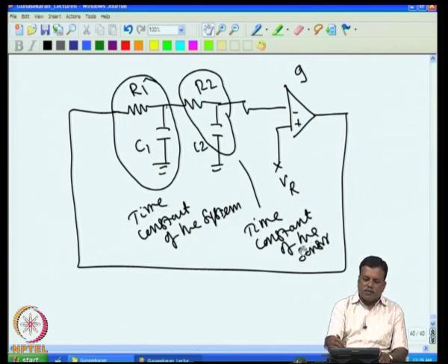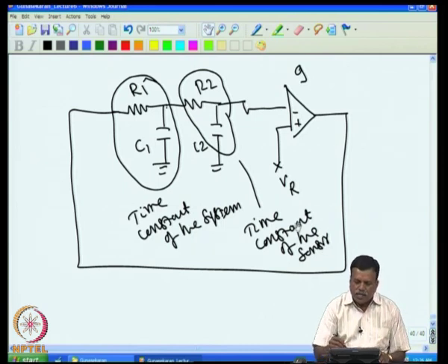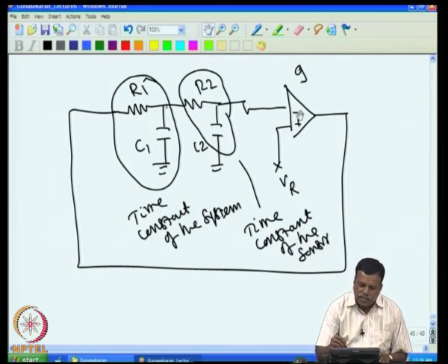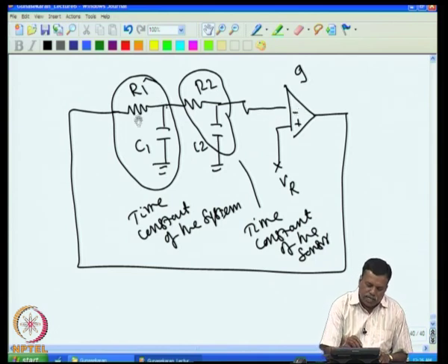That means we got a phase shift of 360 degrees, which is one condition required for an oscillator to work. So, we already produce a 360 degree phase shift. Another condition for the system to oscillate is that the loop gain should be more than 1. We had given some gain here, but these two are actually acting as attenuators: if I give an AC signal of some frequency, say 1 volt amplitude, then at this point I will have only a reduced voltage.